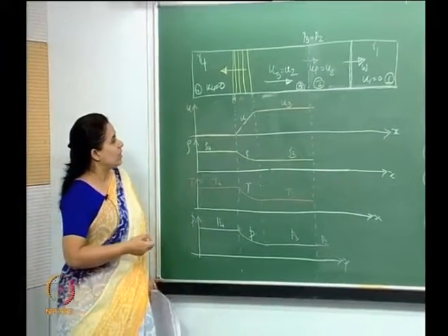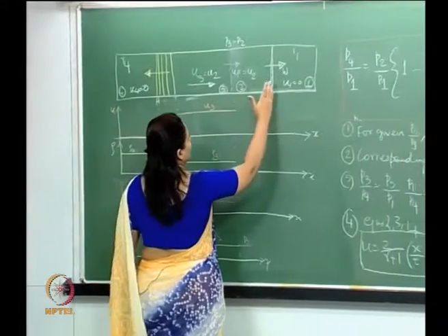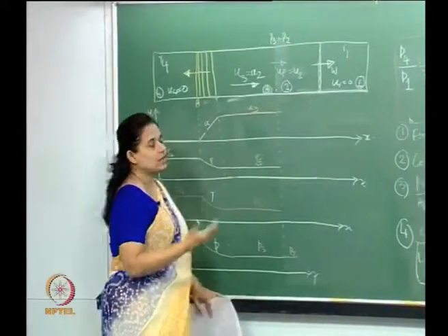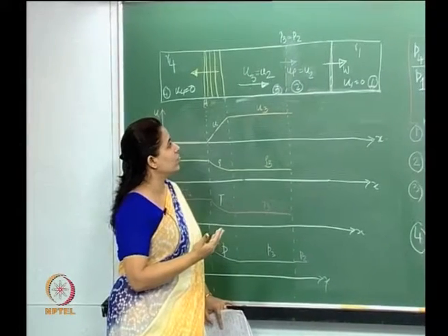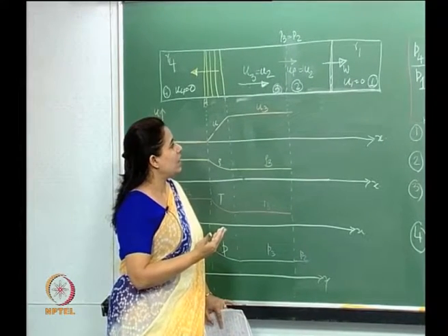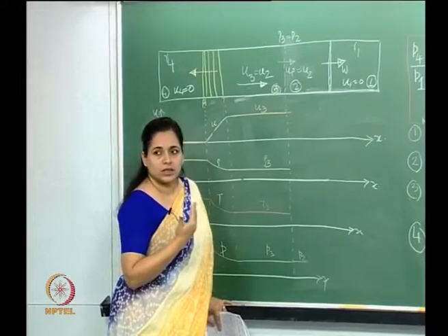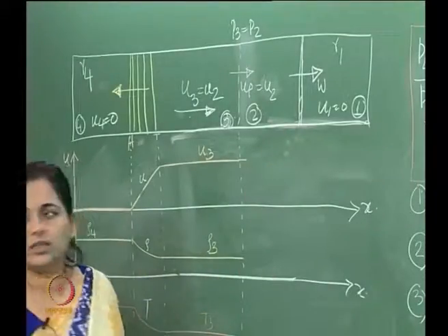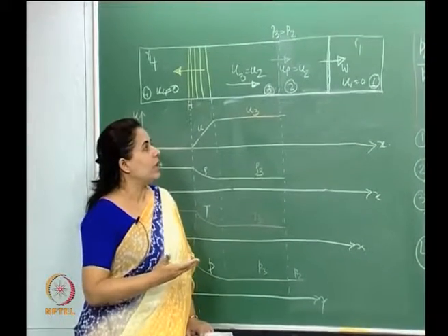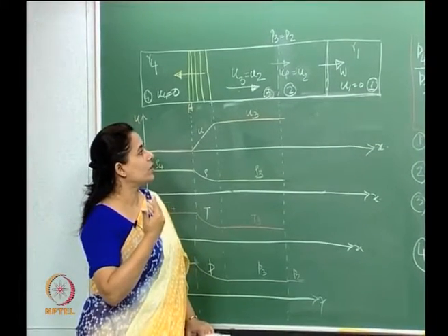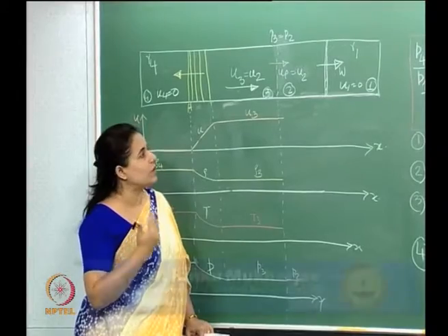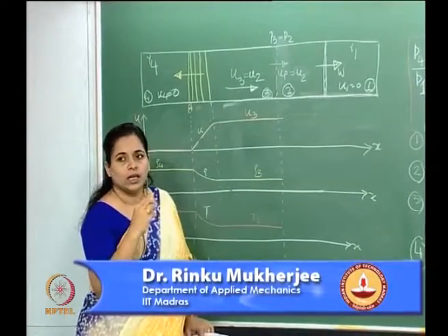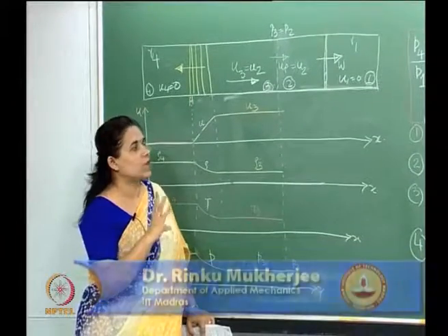Now, we will see different applications of these characteristics in the next couple of lectures. Also, what we saw here for the shock wave is that this is an unsteady motion. The way we solve for properties in this case is to change the reference frame, so as to get a picture which we were familiar with earlier, the steady case.